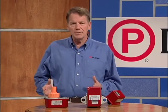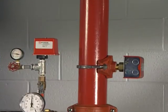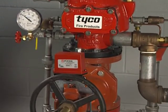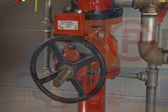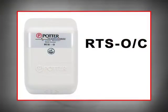Dry pipe sprinkler systems are usually installed in unheated buildings or where there's the possibility of sprinkler pipes freezing. While the pipes in this type of system remain dry when the system is not active, the dry pipe valve and other equipment the system is connected to do retain water and must be housed in a heated location or enclosure. This heated location should be monitored by a Potter RTS, room temperature switch, to notify of a potential low temperature condition.